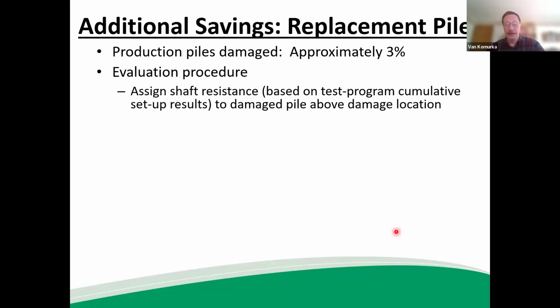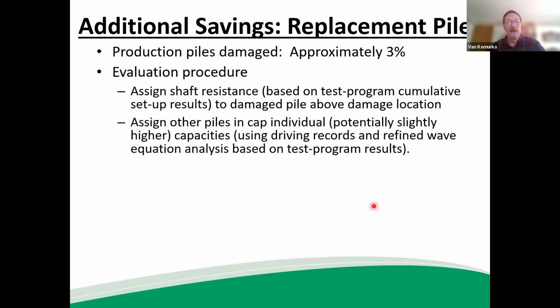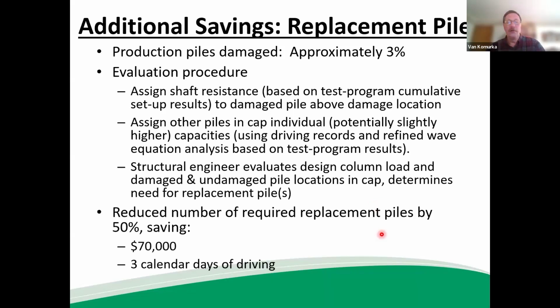Just again, for time, know that we developed a method of incorporating the test program results, particularly the shaft setup profiles, cumulative shaft setup profiles, to assign damaged piles reduced capacities. And this kind of presents how that was done. And again, it's in more detail in the paper. But just know that because we had the test program results and because we characterized the setup the way we did,